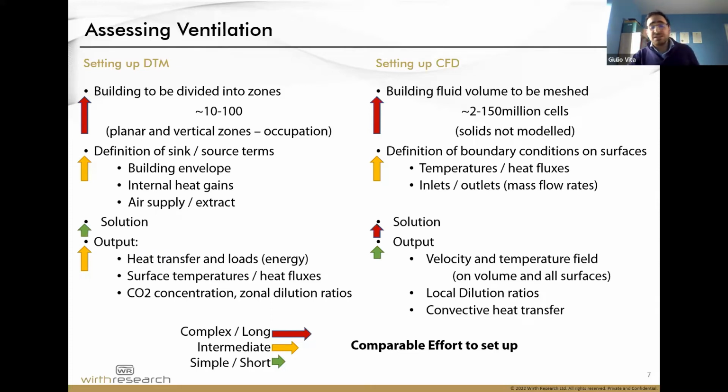Then you define the sink and source terms that drive your thermal behavior in the DTM. In the CFD, this step is normally the fastest one, but still you need to make sure that your assumptions are correct. The solution step is very fast in DTM, whereas in the CFD it can be quite long, days to achieve a solution, but normally all that is required is for the individual to wait for the solution.